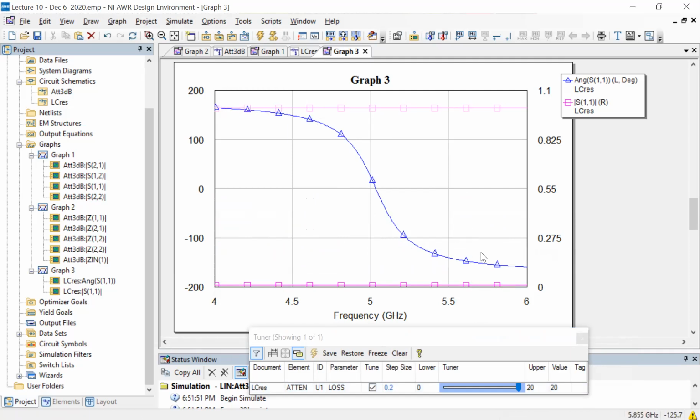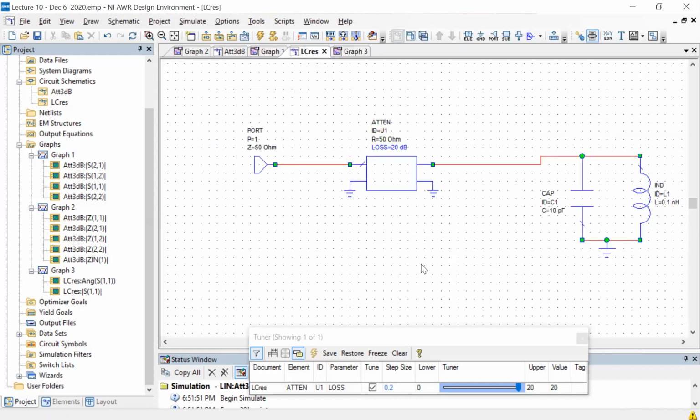And this is because Microwave Office is just a numerical calculation. But what's going to happen in reality is that the signal to noise ratio on this phase measurement is going to suffer dramatically. Even if you put a lot more power, unless you're able to compensate for both the incoming and outgoing power, you will not get back the reflection without suffering from signal to noise ratio.